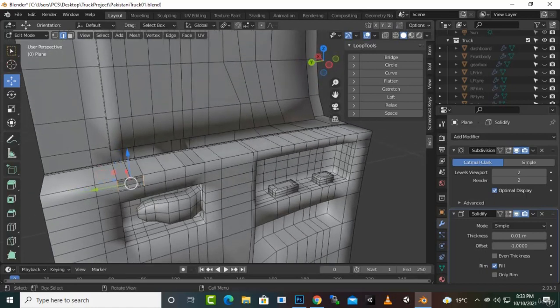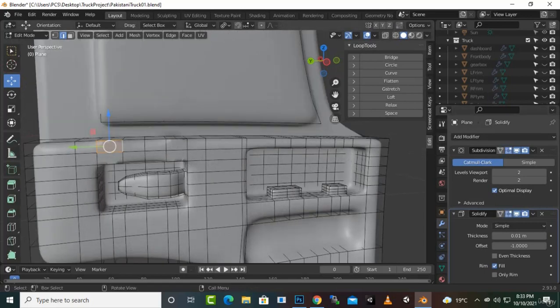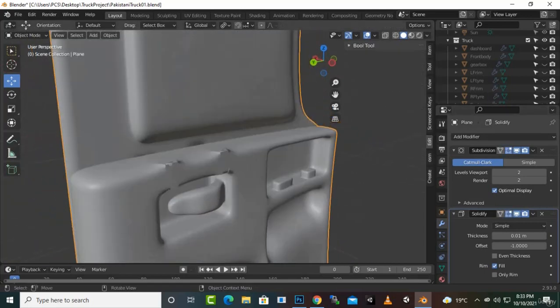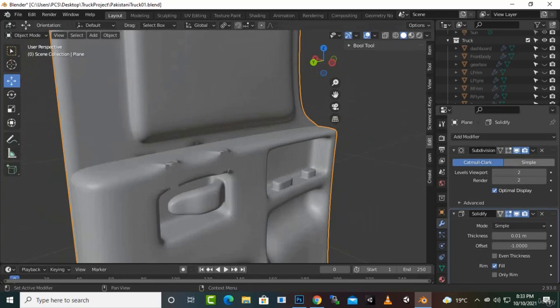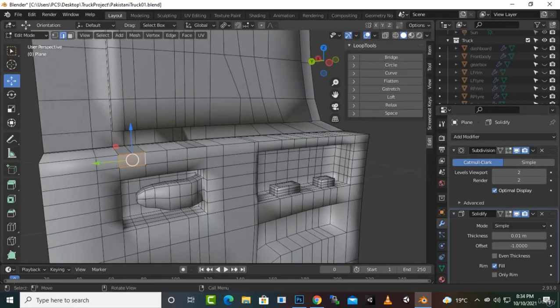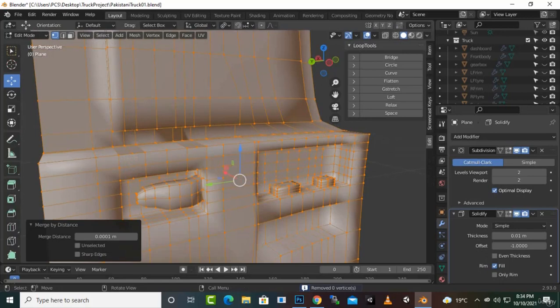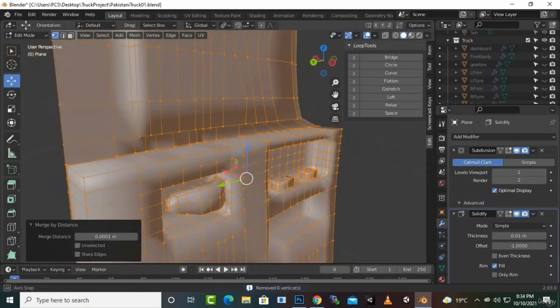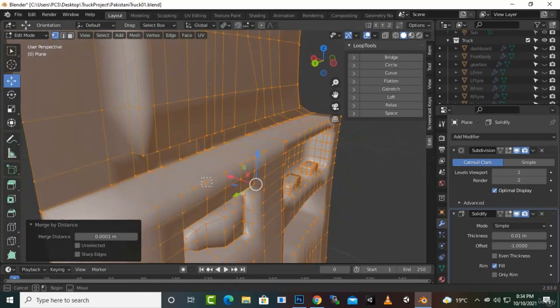So this one and this one, and F4 loop, and now you can see it's quite suitable, but vertices are not joined here. That's why we are still getting the problem. So for that, for example, if we go to vertices and select everything and merge vertices by distance, 0 vertices added, so the problem is that we have some double vertices here, I think.